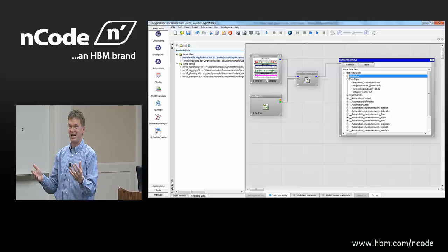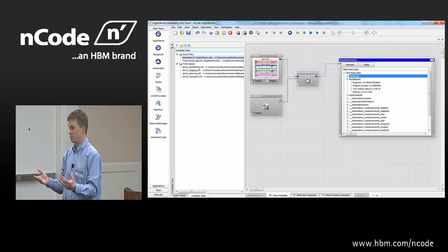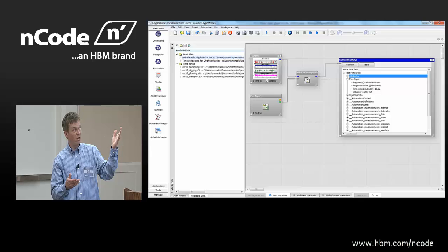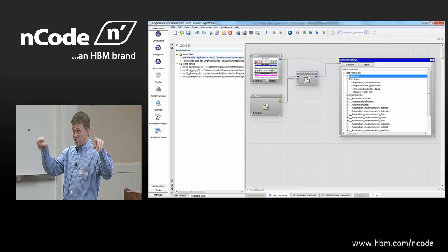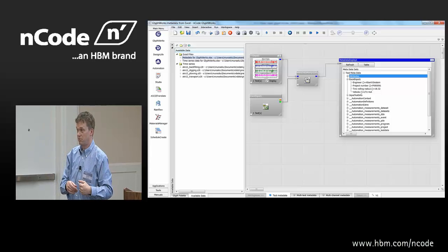How do you refer to metadata in a glyph or inside a report? Pound signs around it, right? So now I have the ability to refer to engineer, and whoever the engineer is in the spreadsheet gets carried through. So my report might say engineered by da-da-da-da, this kind of stuff.